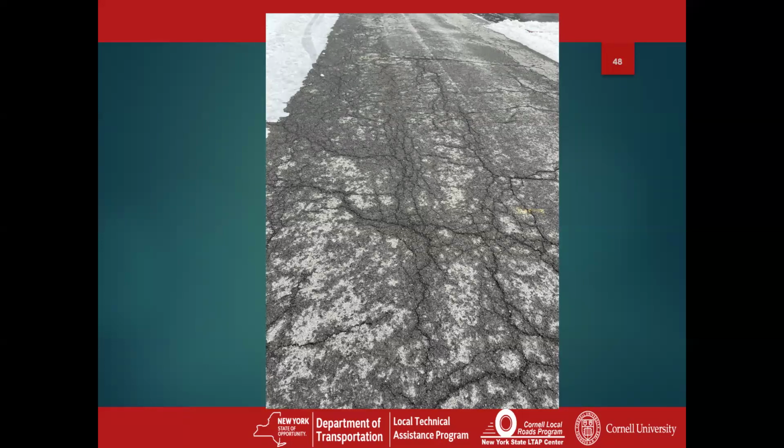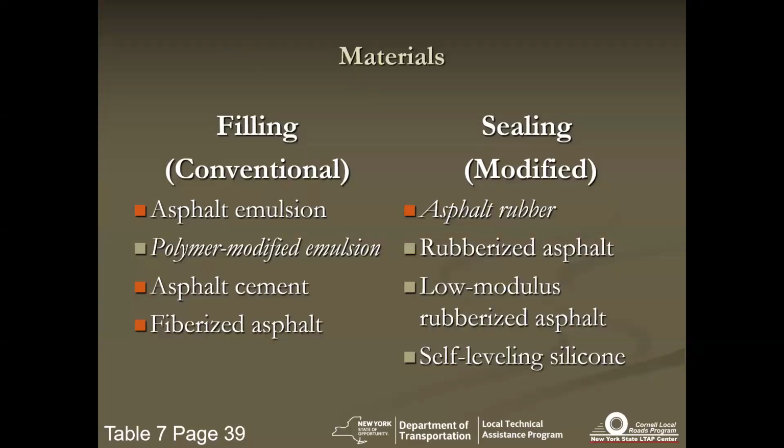Okay. And folks, when you see your pavement looking like this, it's definitely not a crack sealing candidate. If it's localized, it's a patching candidate. If it's extensive, if it's high density, you've got to be doing some sort of rehab.